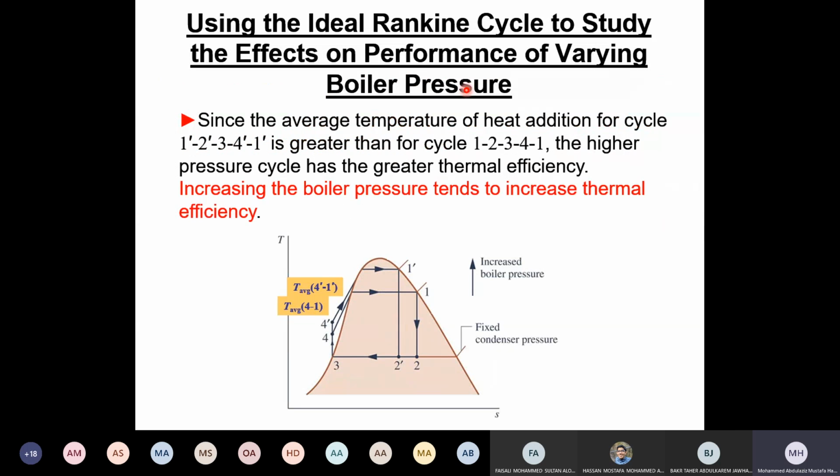Why is the improvement here? In this part, it is that we have raised the temperature at the boiler inlet, and therefore we have less irreversibility here, and this is the reason. So yes, you are on a point, yes, we have improved. This is like regeneration, or what we say here, reduce the temperature difference or reduce the irreversibility in the boiler. I will talk about this next time, inshallah. But you are right, this is towards regeneration. Any other questions?